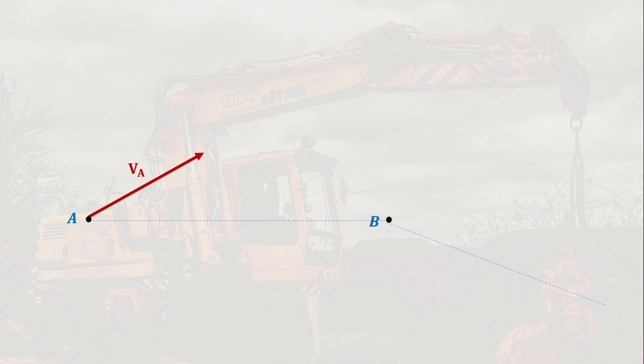So our goal is to get the velocity of B, the direction of the velocity as well as the magnitude. So the magnitude of A here is actually predetermined. Say for example, you determine that the velocity of A is 100 meter per second, and then you use 1 inch is 100 meter per second. So say this is 1 inch. So you just draw it here. So that's how you use the velocity scale.